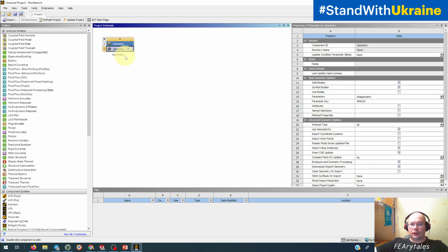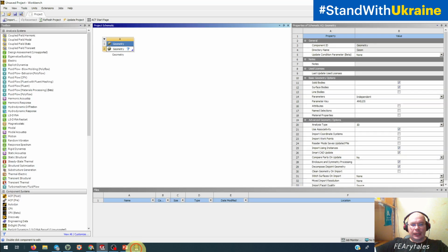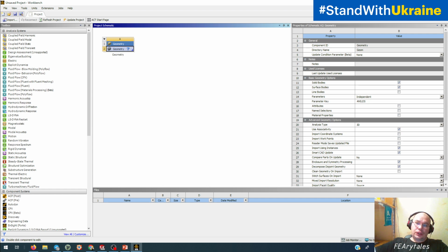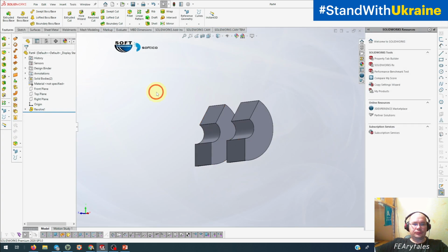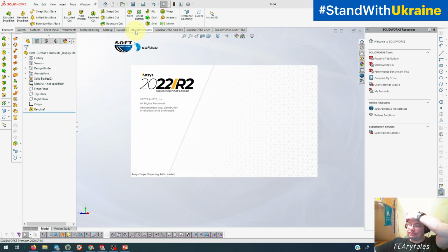And if we choose this object, we don't see a link to our model here. And even if we open our SolidWorks, press save and say please update, something like that, you will not obtain anything from updating. So you need to close this one, don't save. Save this object, we already saved it, and start Ansys Workbench. And now you will have a geometry.